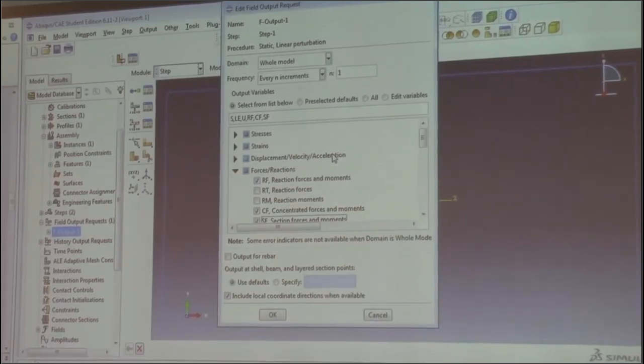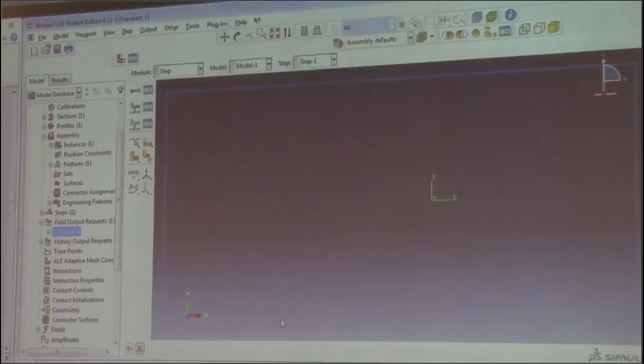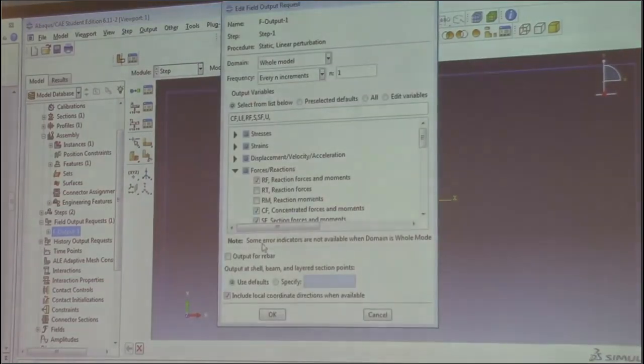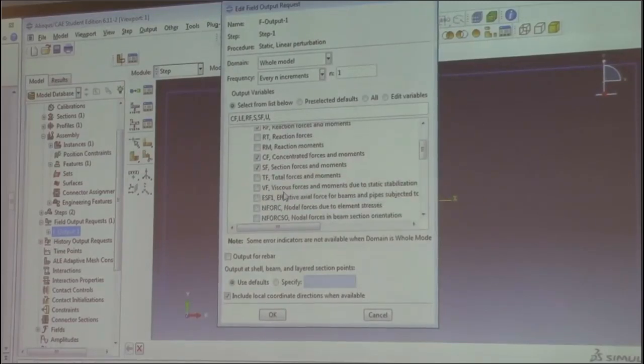In the future, if you have a very complicated project, probably in step 1 I add the horizontal force, and in step 2 I add the vertical force, and you can create as many steps as you want. That is the purpose of steps. Okay. And it's just so that ABAQUS can walk through it step by step. Yeah. So, did I add it? Okay, added.